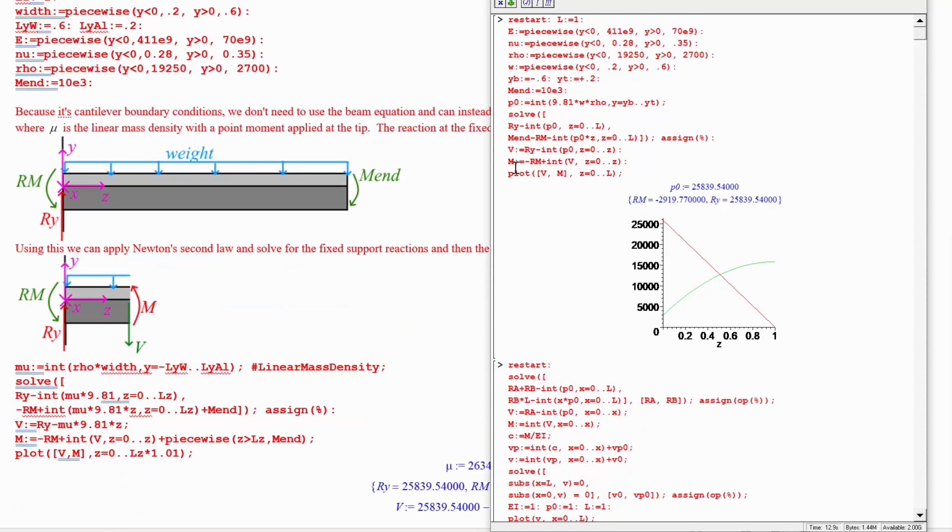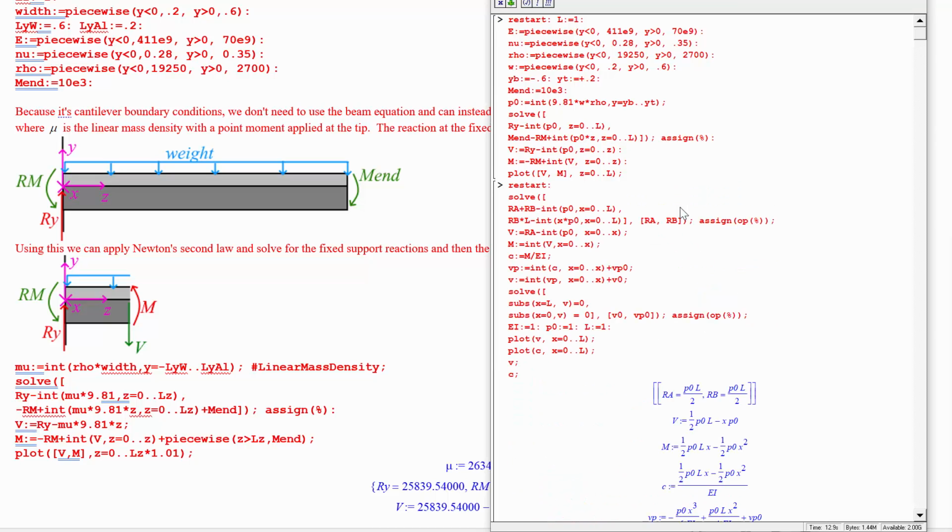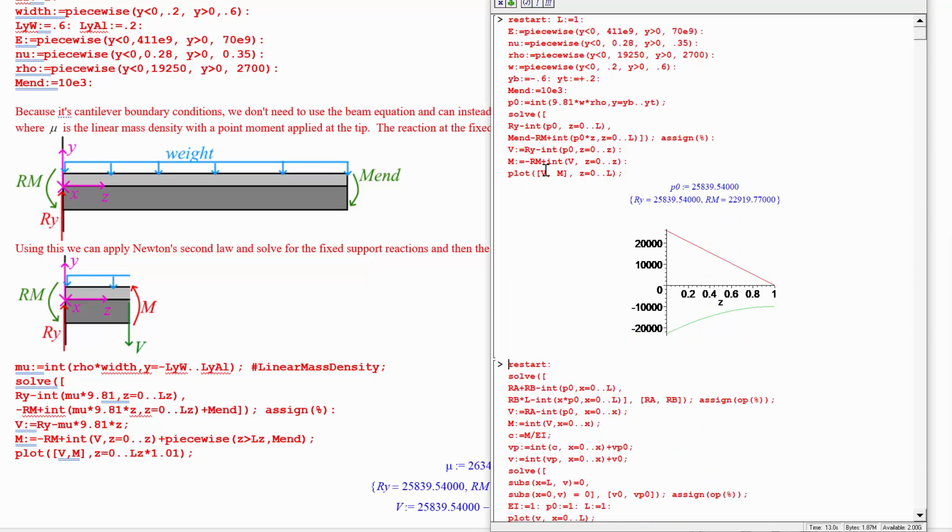Aha, I found something. So this torque equation is wrong. The equation that we put here, we made a sign error. Or at least I did, I'm not sure if you did, but the moment that we applied at the end here is positive because we said the positive x direction is this, and that's the same way that the weight is making it move this time. So we should have a positive integral of this thing added there. Because we had that inconsistency, it was leading us to something that was not quite right.